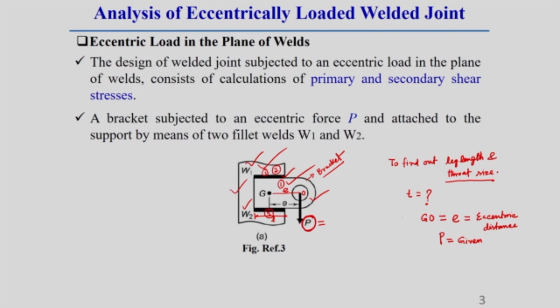First of all, the steps we have to follow for finding out the throat thickness: first and foremost is to find out the primary and secondary shear stresses. After that, based on these primary and secondary shear stresses, we find out the throat thickness. How to find out the primary and secondary shear stresses, I will discuss first. After that, I will show how to find out the throat thickness.